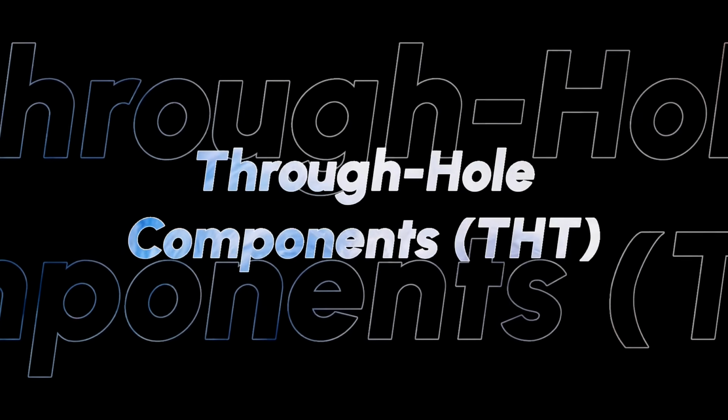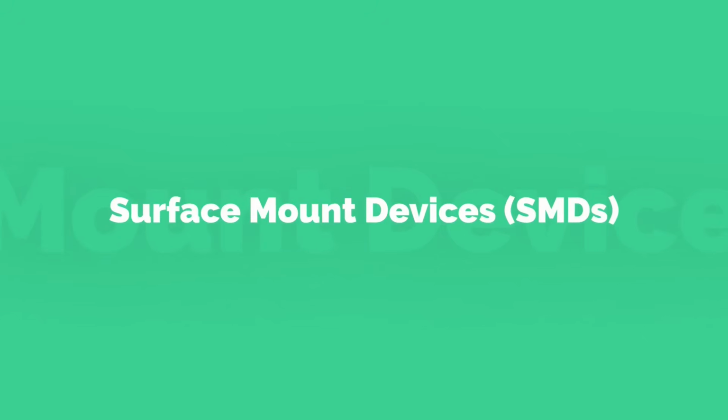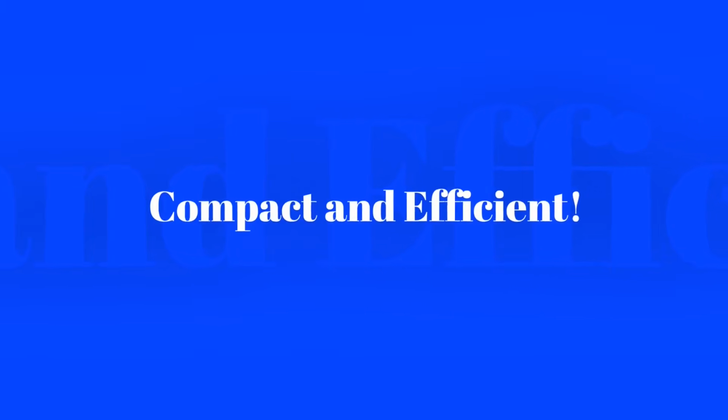Through hole components, also called THT, have long leads that pass through the holes in the PCB. They are perfect for beginners because they are easy to solder and ideal for projects that need mechanical strength such as Arduino boards or power circuits. Surface mount devices, which we call SMD, are much smaller and are soldered directly onto the surface. These components are placed on one side of the board and are commonly used in compact electronics like smartphones, wearables, and IoT devices. They make automated manufacturing faster and allow more components to be placed on a smaller board.